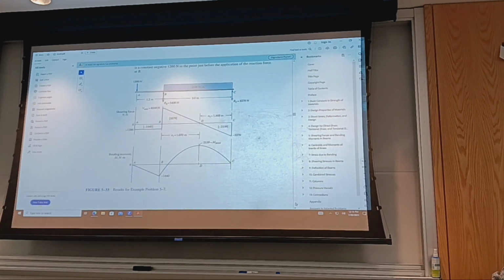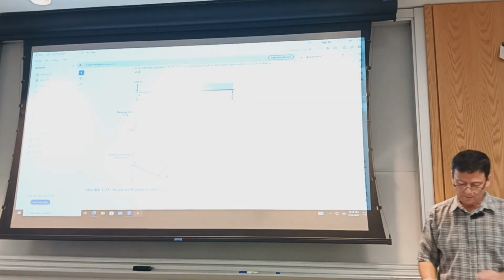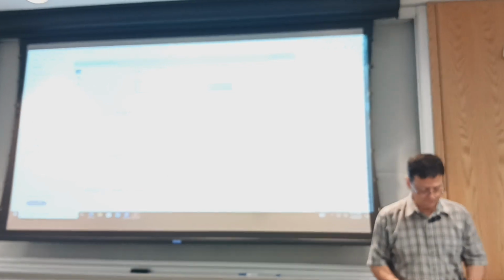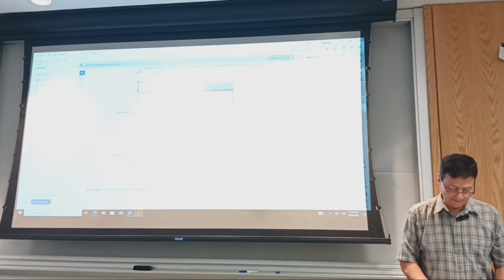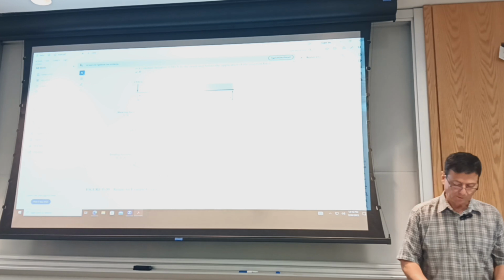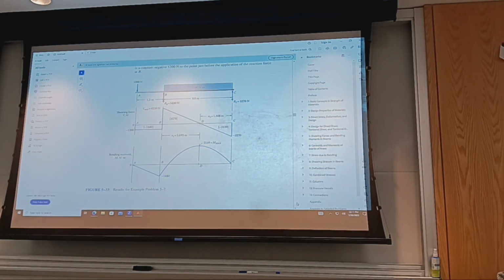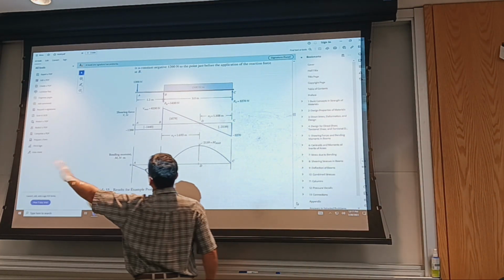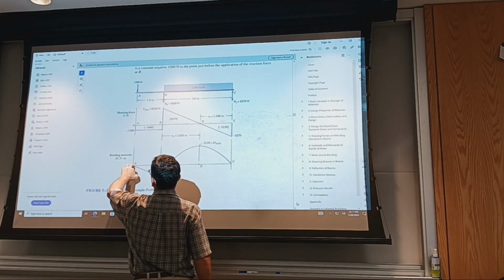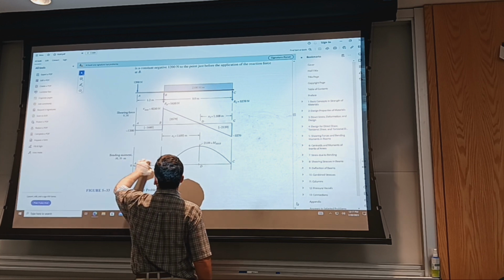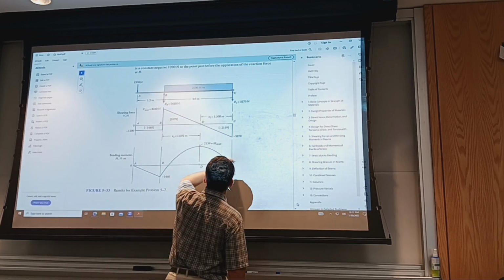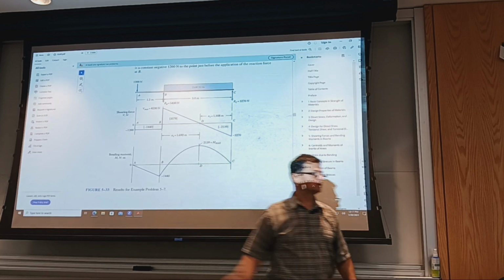So remember, the book goes through the process of explaining how the area method works. There's a proof for it, taking the infinitesimal piece of material that you're analyzing, and then you integrate between the origin or other convenient points. Usually we start from all the way to the left and call that origin, and then we define an x, a current longitudinal coordinate that positions a current section along the beam.